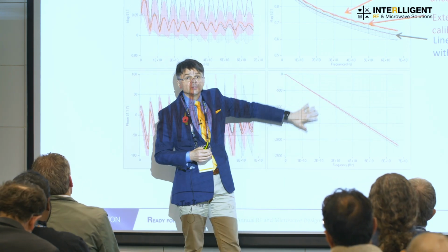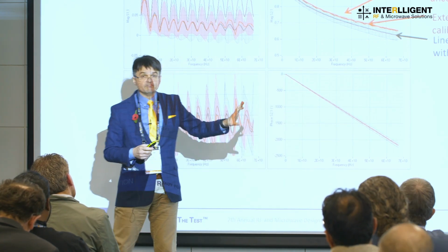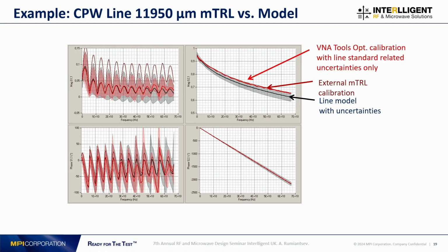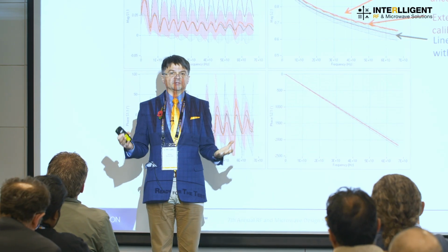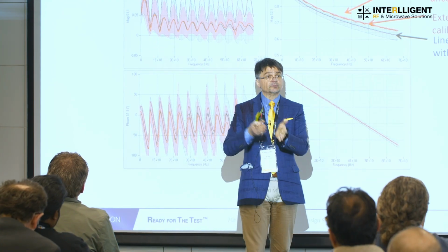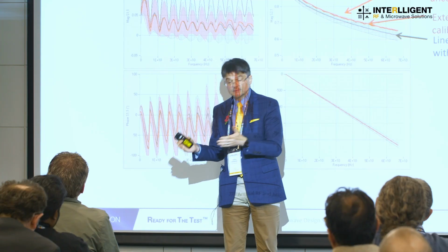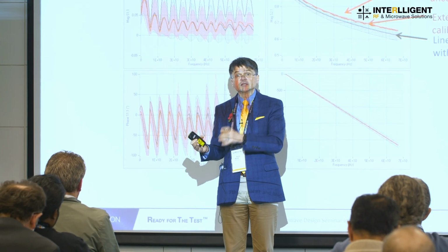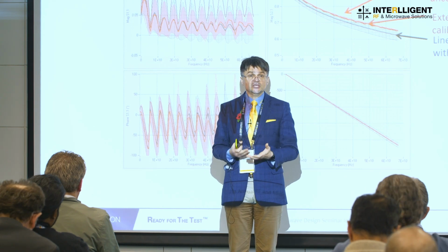And here's an example using the software from METAS, which is called VNA Tools. What we tried in this experiment is to estimate possible uncertainties of our calibration standards, which come from the manufacturing process. We cannot establish the full chain of traceability, but at least we can estimate it when we manufacture calibration standards. Due to the instability of the manufacturing process, every set of calibration standards can be slightly different, and we know these variations.